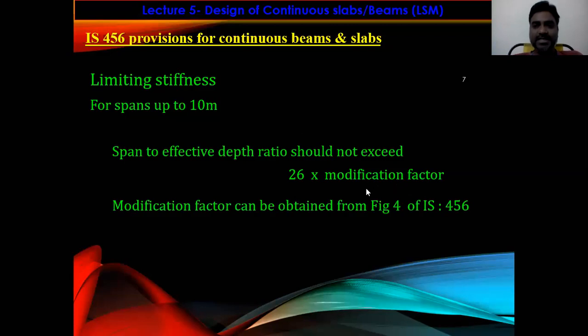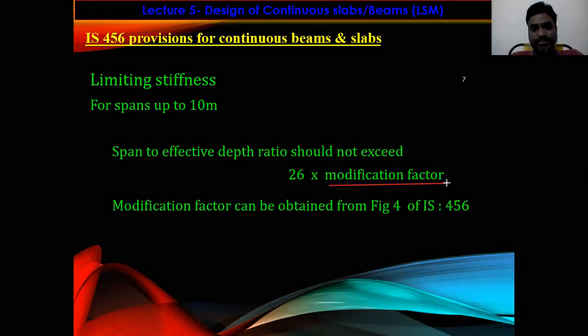As we discussed in previous classes, for checking of stiffness or deflection, you need to determine the modification factor based upon the reinforcement provided in tension zone.